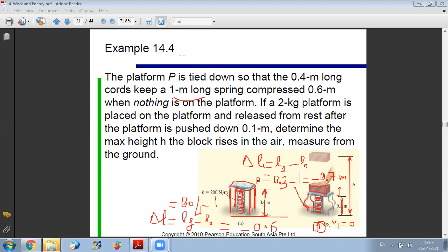So in case you want to take an intermediate case, the intermediate one will be when just the block will leave the plate. Okay? Because look what will happen. In a first stage, the plate and the box will move together until the spring reaches 0.4 meters. Once the length of the spring reaches 0.4, the spring cannot follow the block anymore because the plate is restricted to be at a distance of 0.4 meter from the floor by the 4 rigid links here.